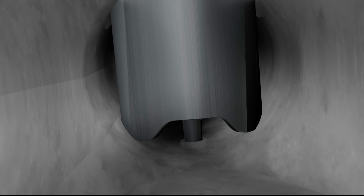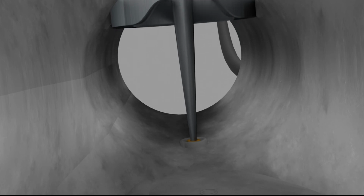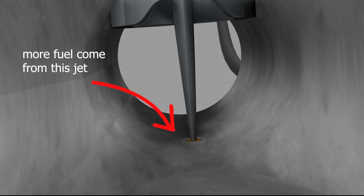With a small amount of air and fuel, the engine will run at low RPM. But if the piston moves up, it will widen the air channel, and the pointed needle closes a smaller area. So with more air and fuel, the engine runs faster.